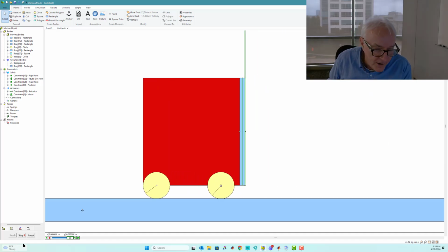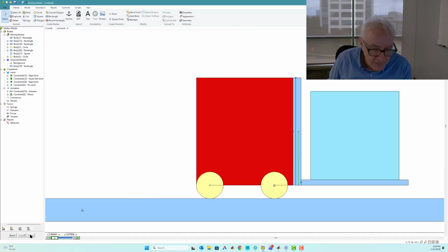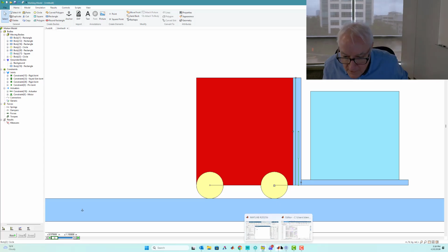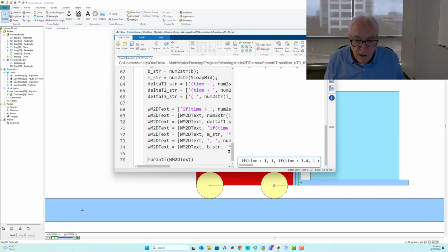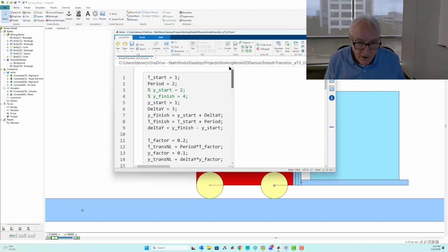So it goes up just fine at a constant velocity, but let's kind of mix the lift and the acceleration of the vehicle. And so we'll go back to my nifty script here. And so this time we're going to set velocity. And I did my homework on this one, so I kind of know that I'm starting off at 0 velocity, but I'm going to transition to 15.7 radians per second. And if I did my math right, that'll be 5 meters per second, which will kind of drive it in the, I'll call it, negative direction.